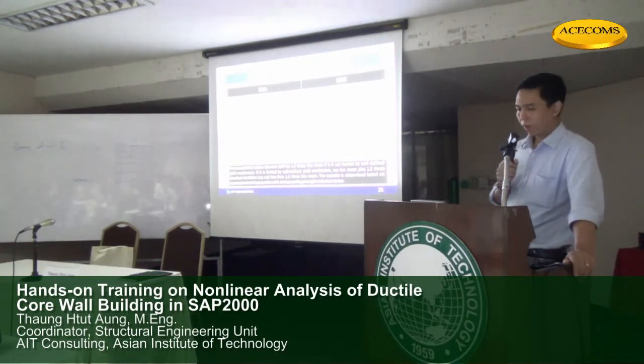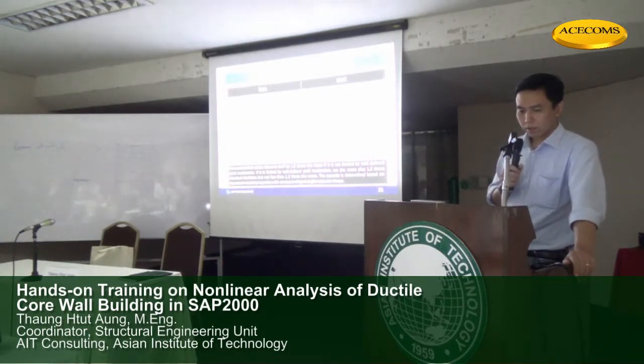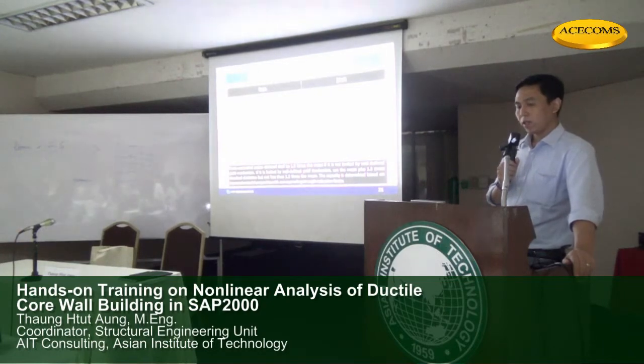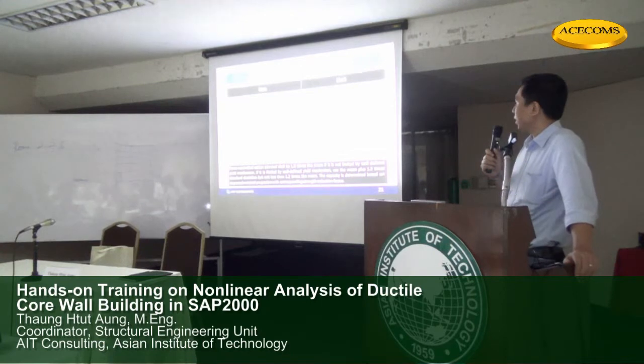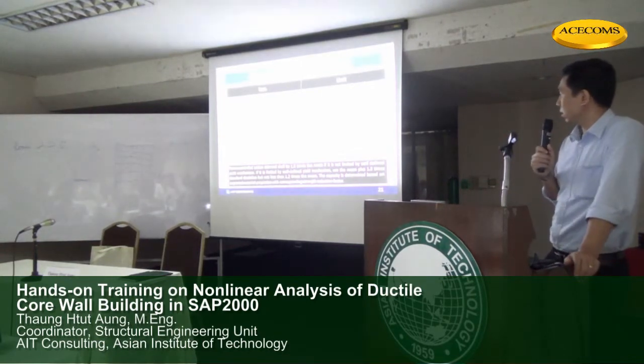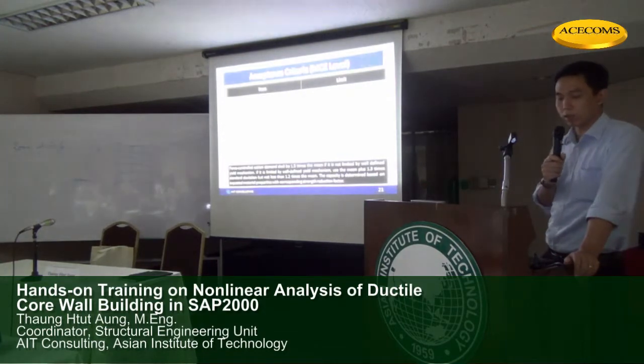So we have to check the shear wall frame distribution and create the load combinations to design the frame to resist 25% for the lower frames only. If the frames are attracting more than 25%, we do not need to magnify the forces. This is for the code-based procedure.